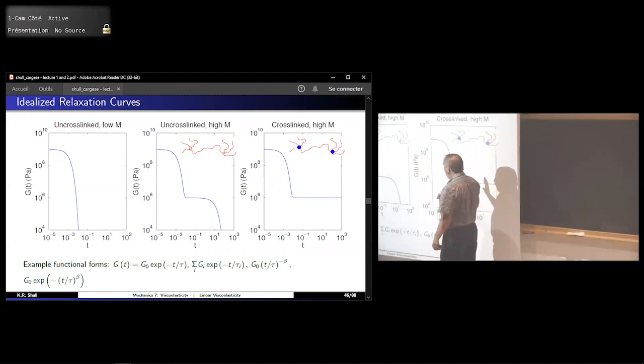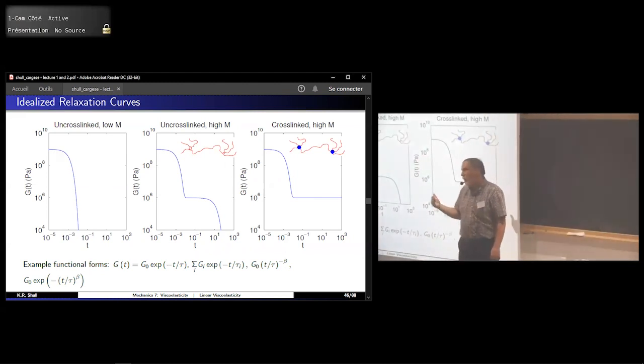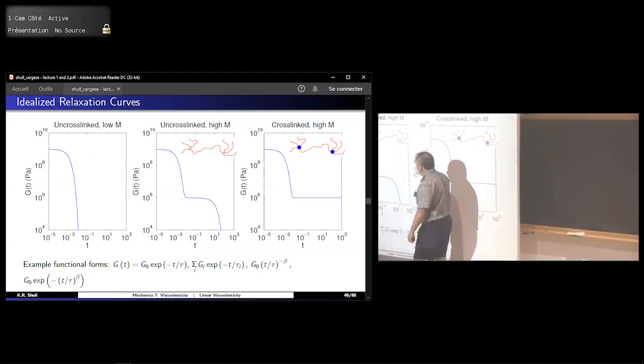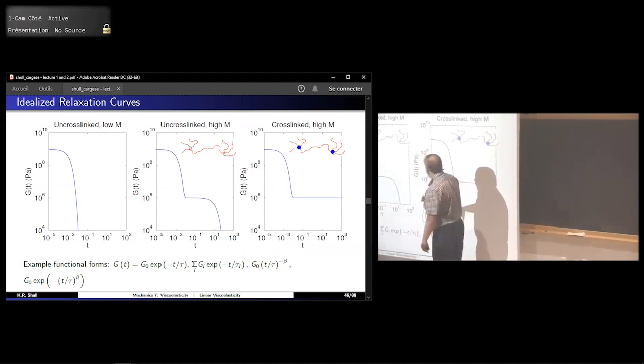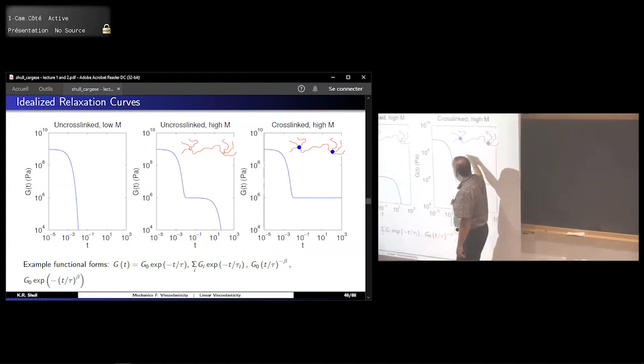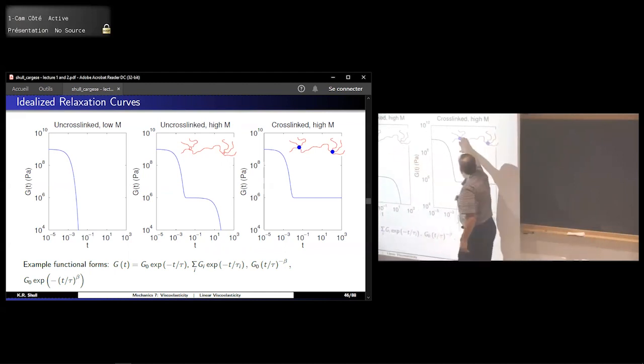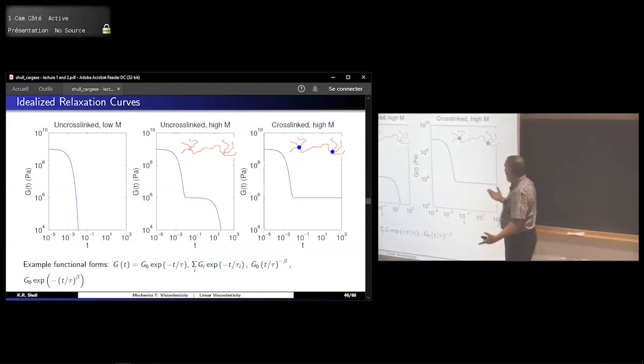But I put this up here to show that the relaxation times typically have some connection with what's really going on physically in the material. So this would be sort of a relaxation from a glass. If it's a high molecular weight polymer, there are entanglements. So there's a longer time it takes actually for these entanglements to relax. And if I cross-link the thing, so instead of just having a physical uncrossability constraint here between these long molecules, I actually have a chemical cross-link that can't relax, and this just goes all the way out to infinity.